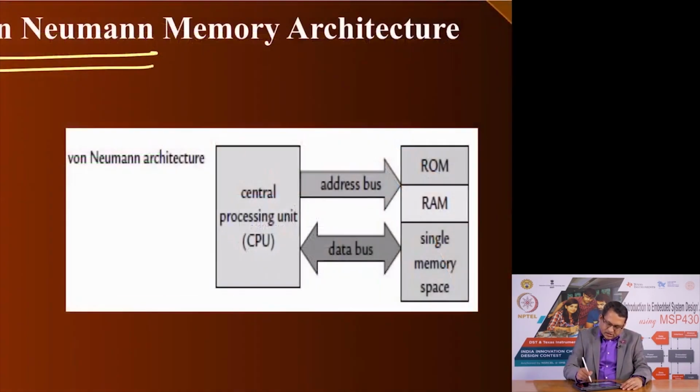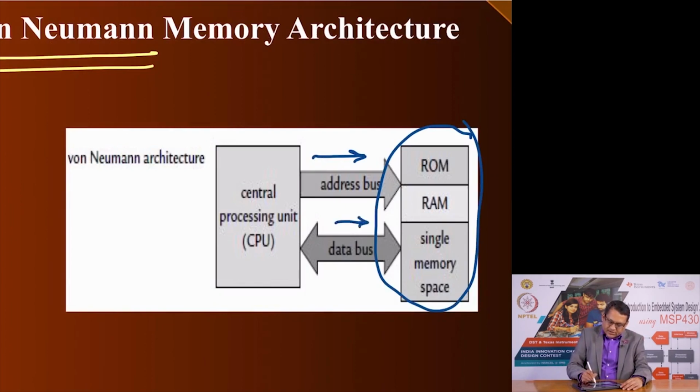This is the memory map, and in a single memory map, using a single set of address bus here and a single set of data bus, you are able to access the ROM, which is the program memory, the RAM and the registers and so on and so forth. So, this is to highlight the nature of the MSP430 microcontroller family.